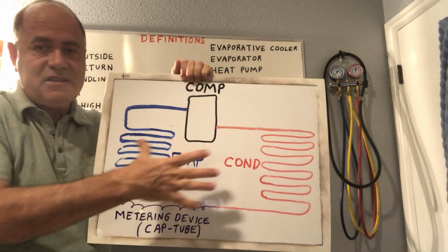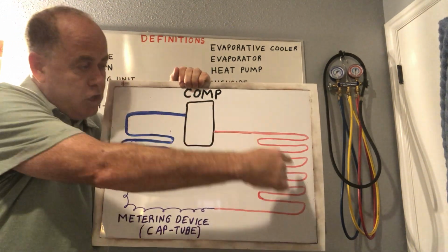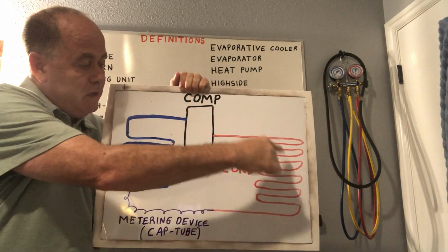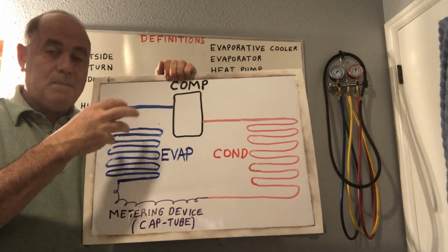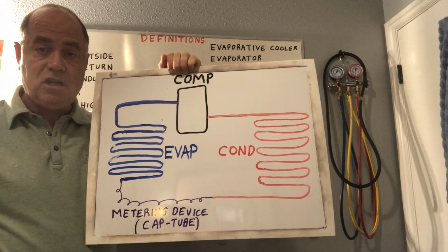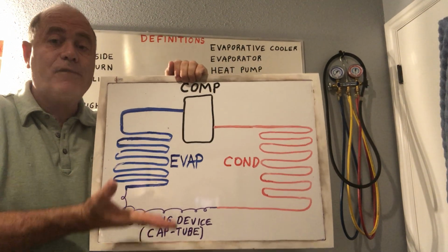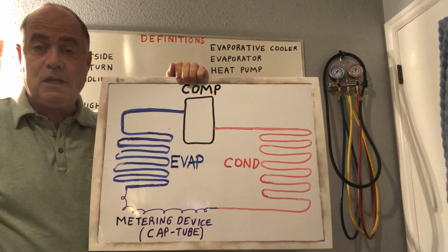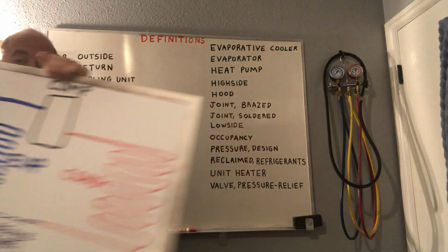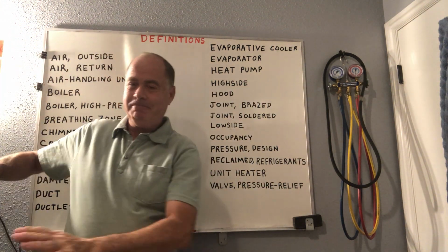And if you take my classes, you'll learn very in depth about the refrigeration cycle going around the system here. Okay, but that's the evaporator, the cold coil that provides the cooling in an air conditioning or refrigeration system, and the refrigerant is boiling off or evaporating inside the piping here in this cold evaporator. Okay? And one thing you'll learn from me is that boiling doesn't mean hot.